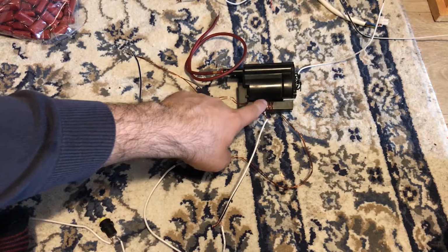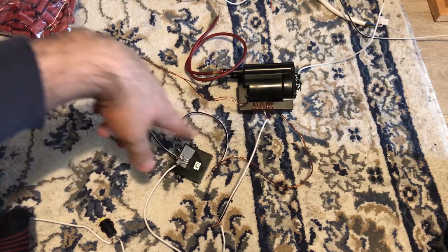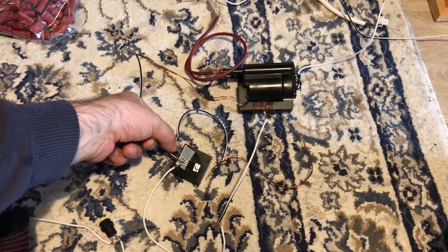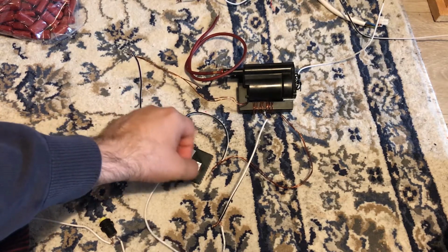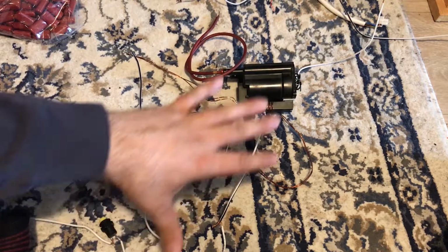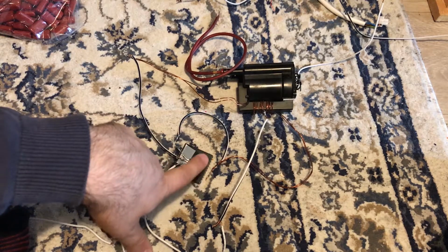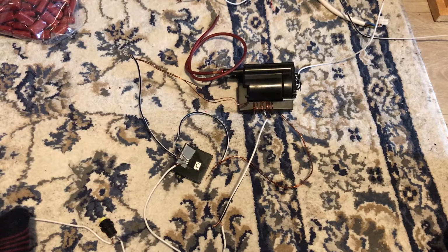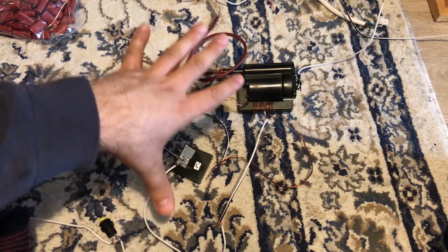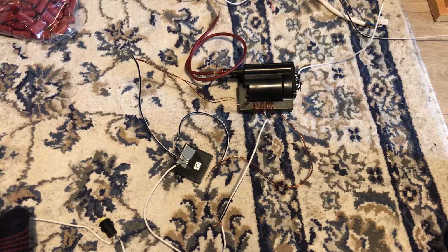For example, the number of primary turns, the number of feedback turns, the gate resistance, the type of the MOSFET, the leakage inductances of the transformer. All the important parameters will be analyzed, and through simulation we can maybe find an optimum point for this circuitry. This is a very common and simple circuitry that people use to produce high voltages, and I really want to analyze it. So this is a separate video which will come in the future.